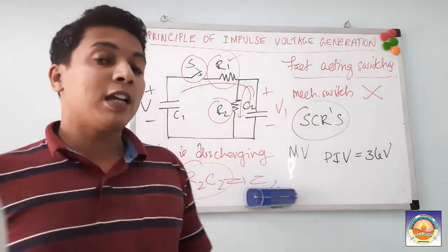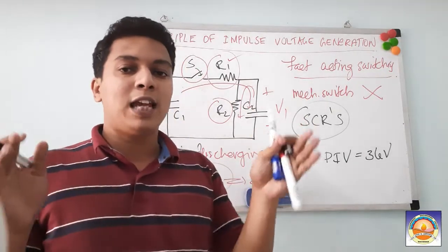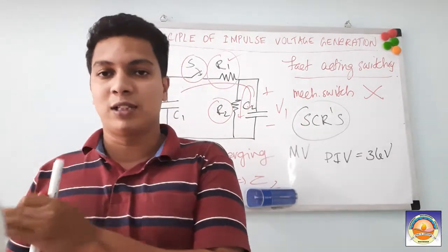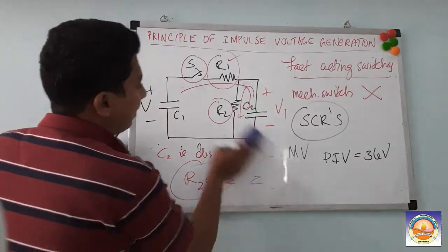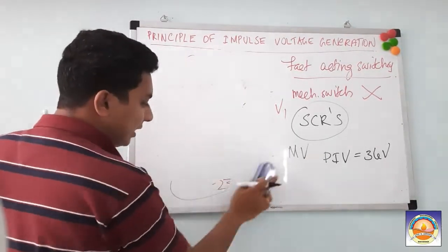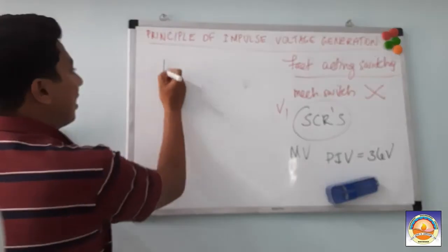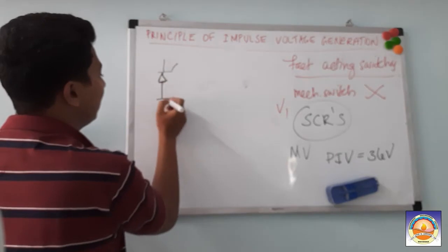So when I am talking about several kilovolts, I have to use a series of SCRs together, all connected in series.